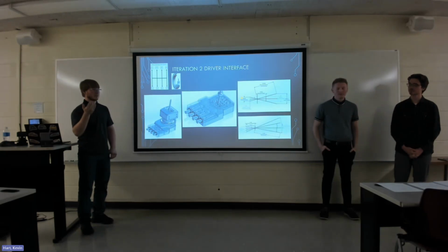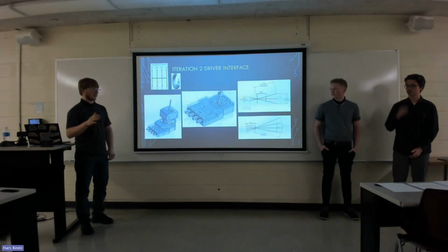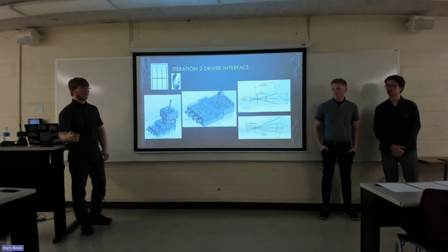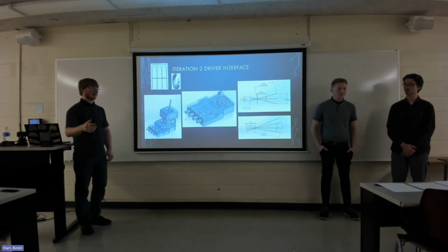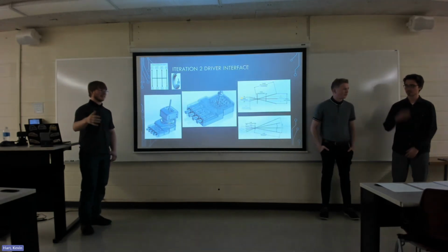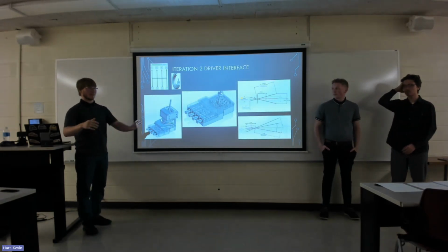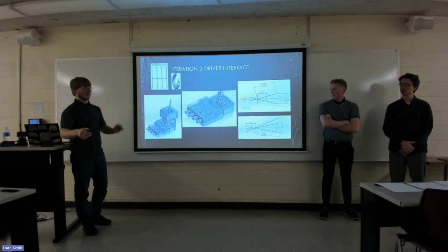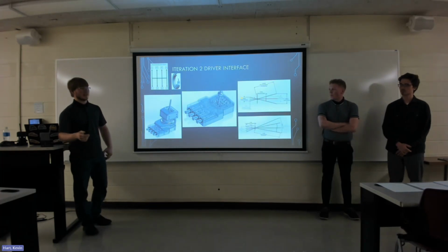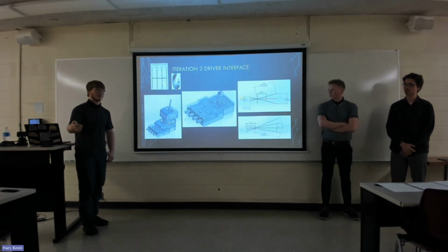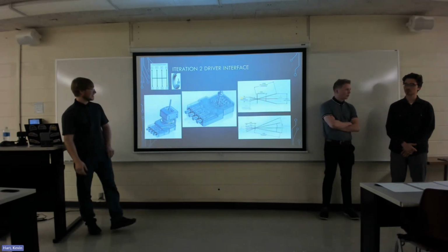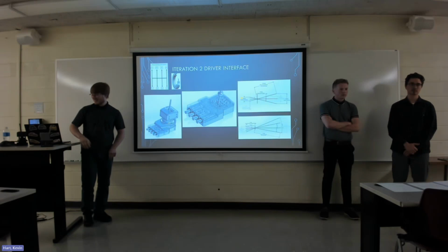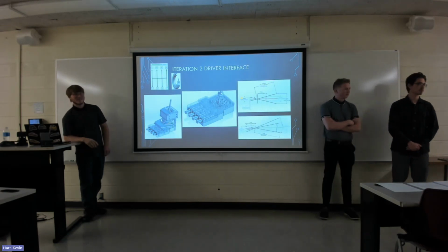The shift speed in the SMG program is directly proportional to the throttle position. So if you're just cruising, it might take almost 2 seconds to make a shift, from putting the clutch in, shifting, and letting the clutch out. That can sometimes be nice because it's very smooth, but it can also feel strange, especially if you're not used to it. For city driving, and the majority of driving, it's not, I guess, fun.